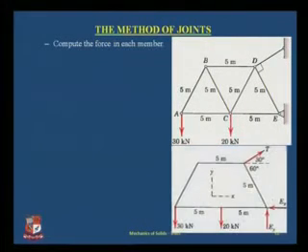This is another example where you can see your truss is cantilever from 2 points. You have joints at 2 points, that is at point E and at point D. In such cases where you have a cantilever section, it is always preferable that you start solving your truss from the cantilever point, because in that case you will always have only 2 members which are unknown here, because the force going downward is known to you.